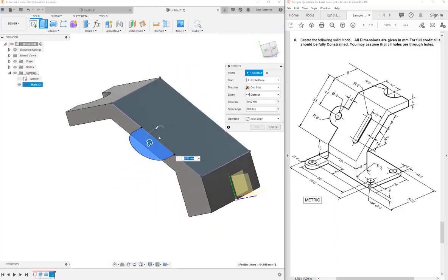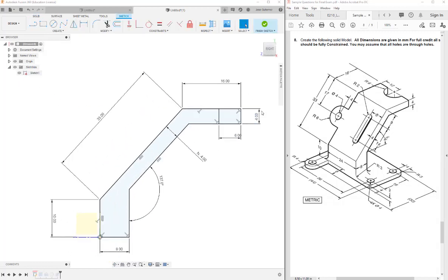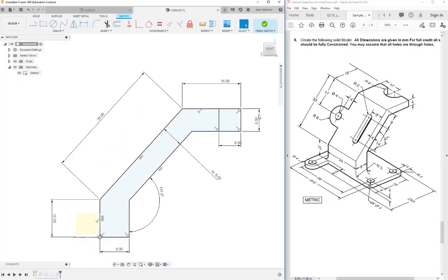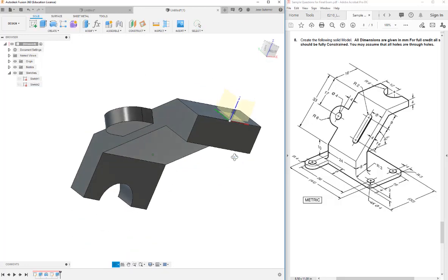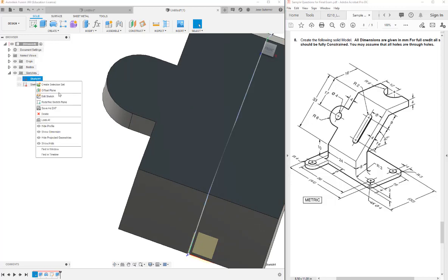And instead of just extruding a distance of -4, I'll show you why I'm not going to do that. Let's just say back in this original sketch, I decided to change this. Remember we discussed we could change that to 6. And what you see here is now this extrude didn't move with that edge. And it's probably the same thickness of material, so we'd like it to be linked. Now we could have made a parameter, say thickness of plate, and then used that parameter in that extrude and the dimension in the sketch. But if you didn't do that,